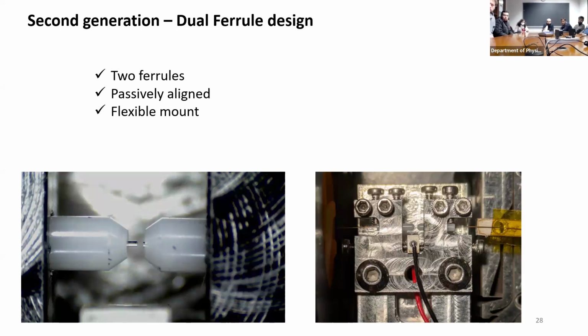And this thing is bendable. If I push through with a screw, for example, it can bend the material. And then I can actually transversely align it, as you asked before, whether I can align the two. But that might be the solution to off-centered profile. If you have an off-centered profile and rotation doesn't make a difference, maybe if you slightly move it, you can slightly make them face each other. So this would be up to like 10 micrometers or so at most of movement.